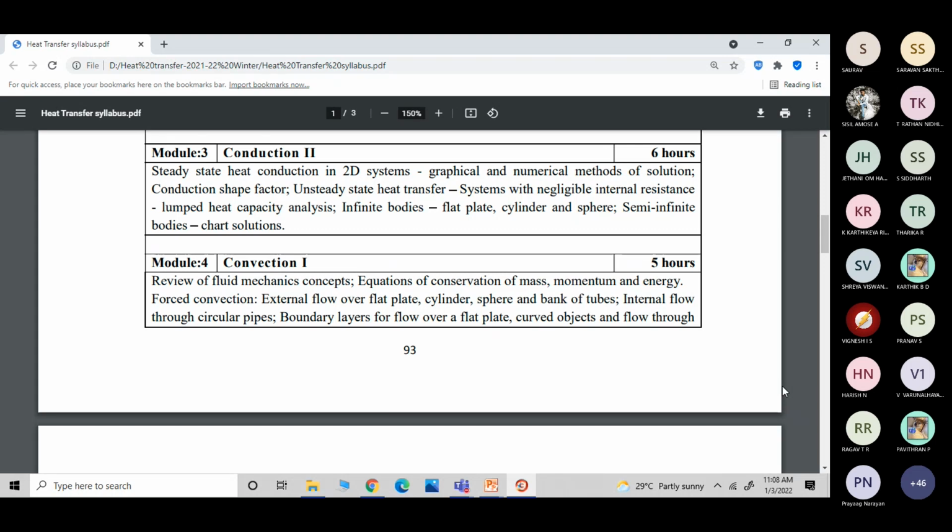Whereas in case of forced convection, you can force the hot fluid. Take car radiators, as you mentioned. The engine will be hot, so a small pump will be pumping the water into the engine, through the cooling water jackets.